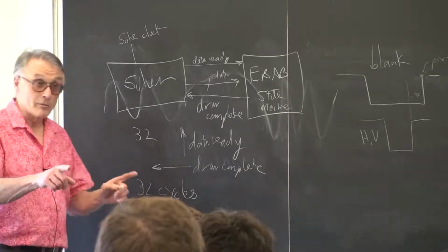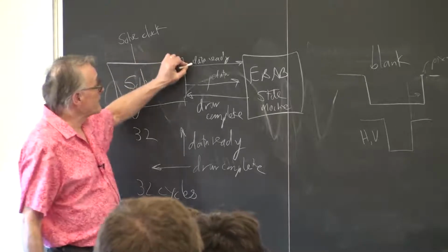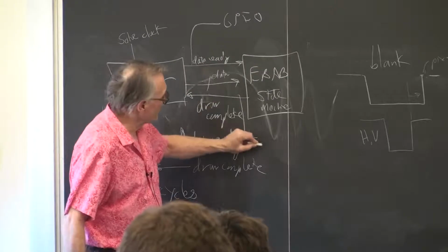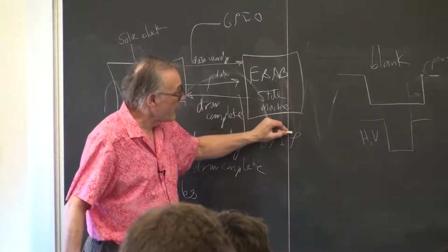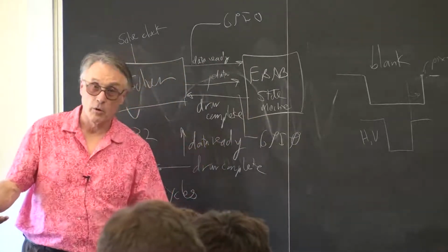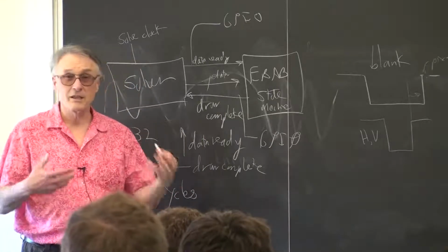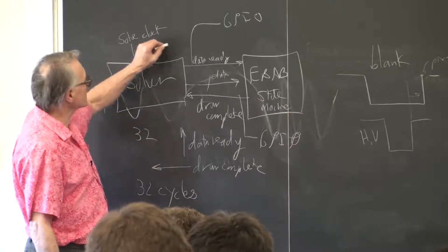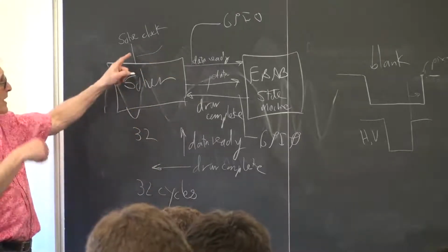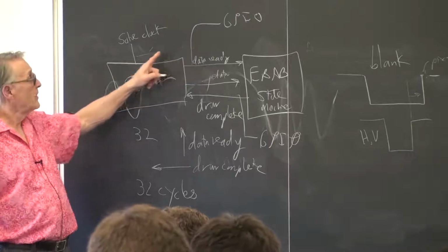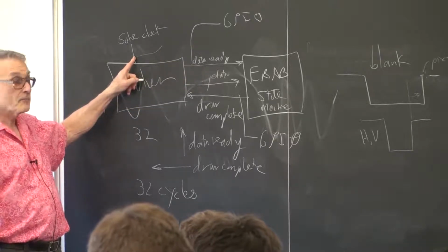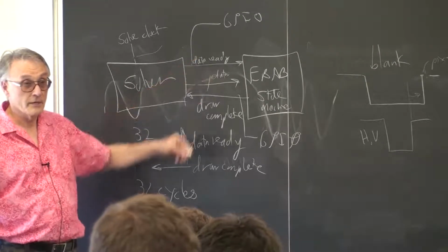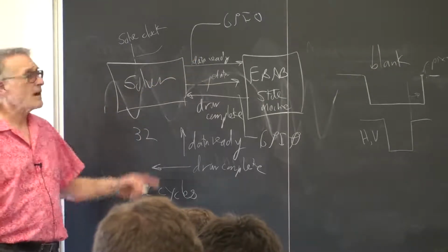And you know, one way of debugging this is to take this line and put it on a GPIO pin, put this line on another GPIO pin, and watch them with the oscilloscope. You should be able to watch that thing ping pong back and forth. Then on the third channel of the oscilloscope, you put the solve clock. This should clock 32 cycles, and then you should get an output. This should assert, right? How do you stop the solver?